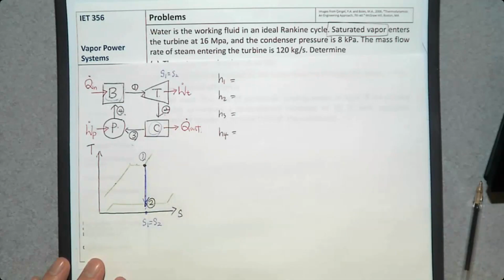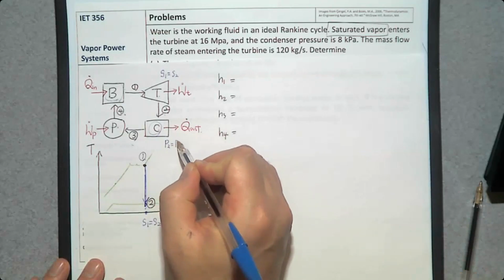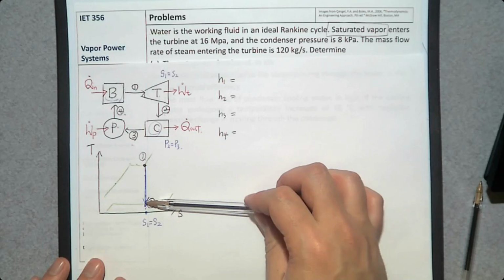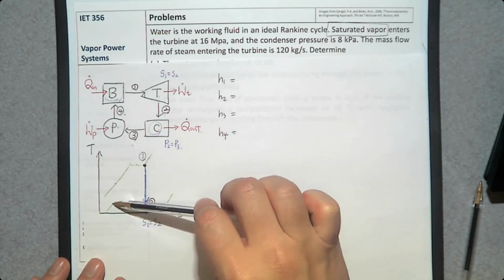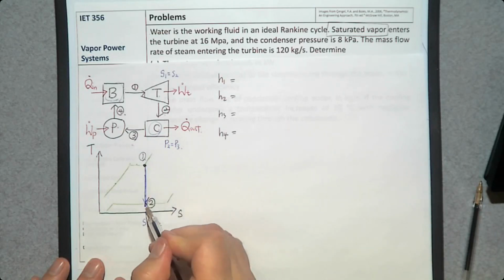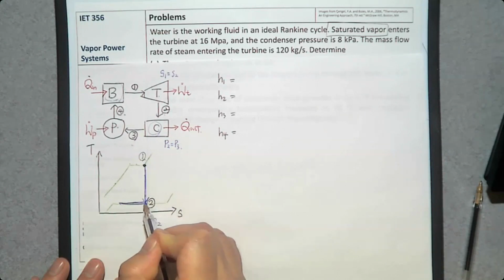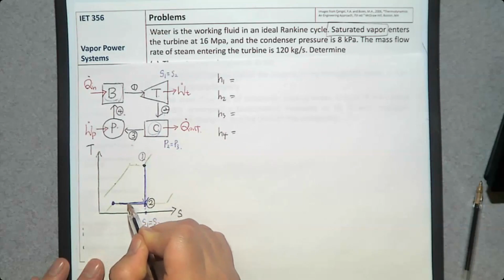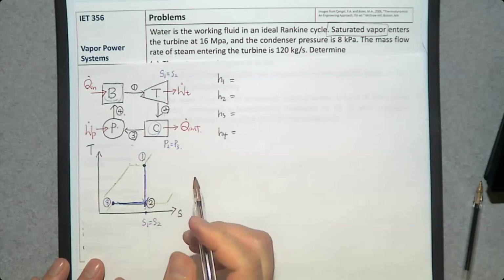The condenser runs at constant pressure. P2 is P3. And if P remains the same, you should be on this green line, right? And we are losing heat, so we move to the left. And the steam can only exit the condenser when it is completely liquid. Number 3, saturated liquid.